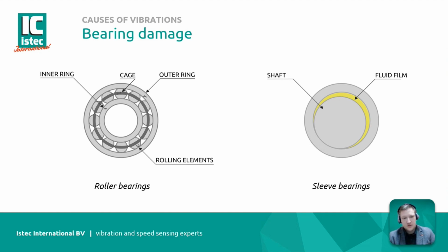In the gas turbine business, there are two types of bearings being used. So for on-wing, it's mainly rolling element bearings. In the industry, it's smaller gas turbines but still have roller element bearings, but the bigger they get, they will all be equipped with sleeve bearings.